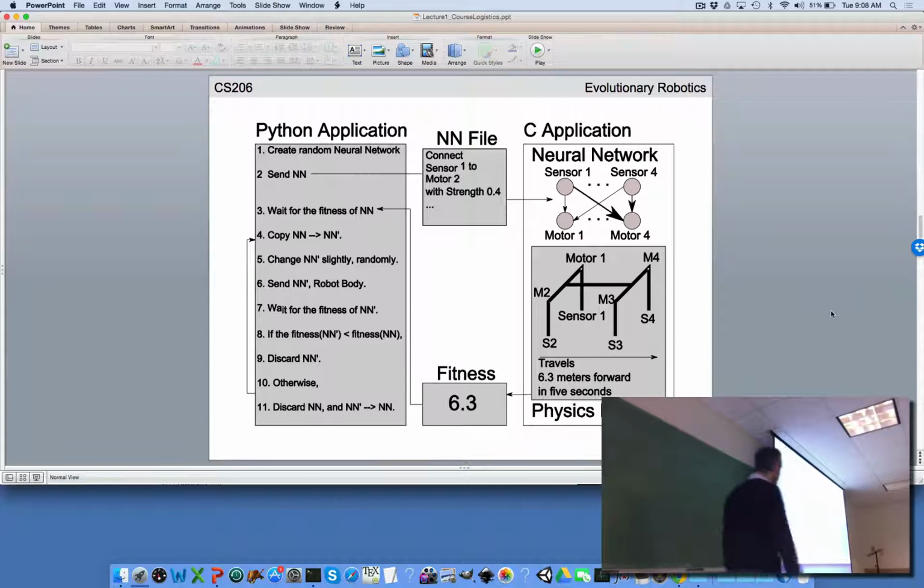You're going to be setting that up in the first 8 weeks of the class. And once you have this loop closed, you can evolve things over here, send blueprints over there, change what you measure over there, get a single number back, which indicates how good that robot is. And because it's an evolutionary algorithm, as you can imagine, the evolutionary algorithm keeps things that have high numbers. Or if we're measuring distance, we want to minimize the distance, then it's keeping things that have low numbers, or things that do well. Everything that does not do so well, the computer deletes, and the things that remain, it makes random modified copies of. It mutates those blueprints, sends the mutated blueprint, sees how well that new robot does, and around we go.